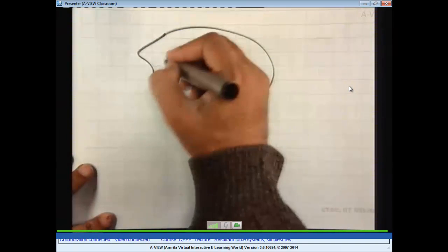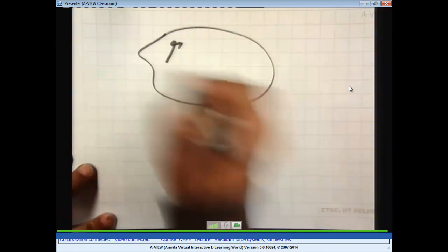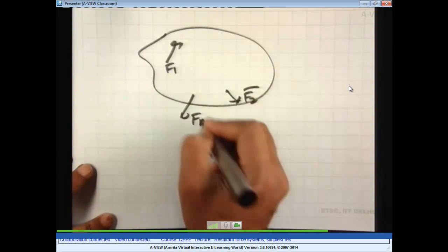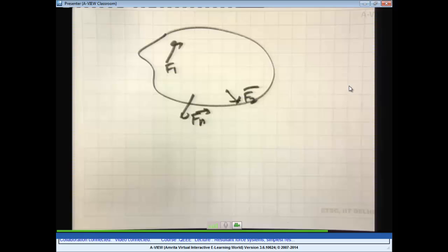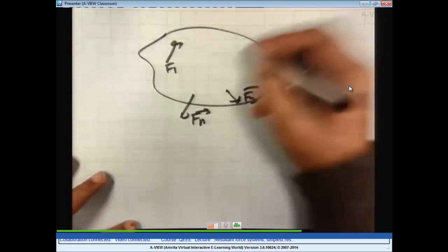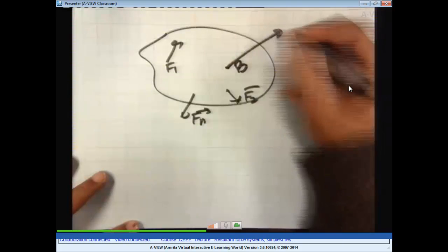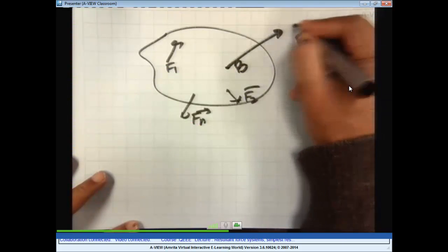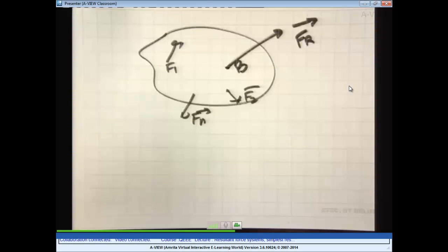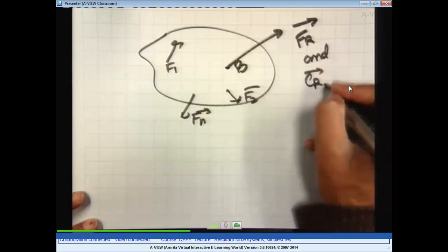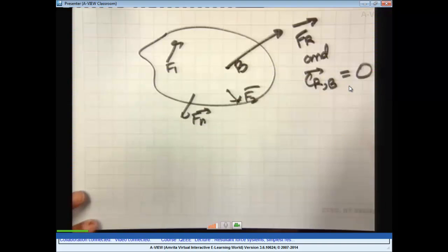Now, what we are saying is that if we have parallel forces F1, F2, Fn, let us assume there are no couples right now, we can shift them to a single point B where the equivalent is just Fr, and Cr at B is equal to 0.